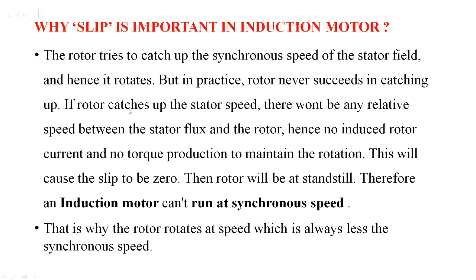If the rotor catches up with the stator speed, then there won't be any relative speed difference between the stator flux and the rotor. Hence, no induced rotor current and no torque production to maintain the rotation. This will cause the slip to be zero.